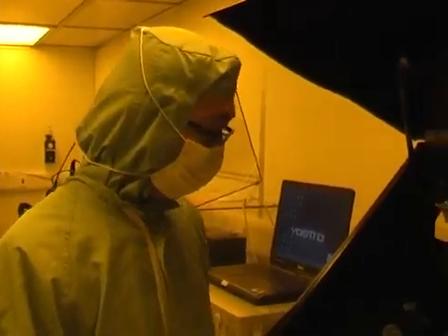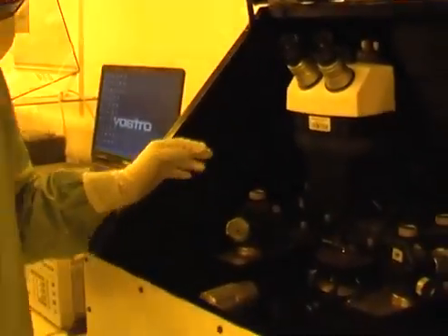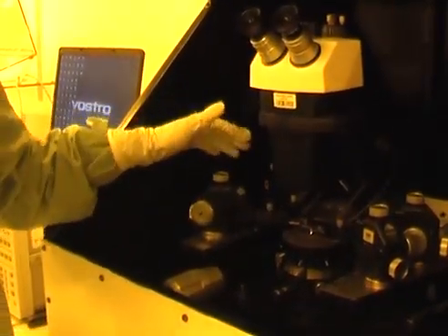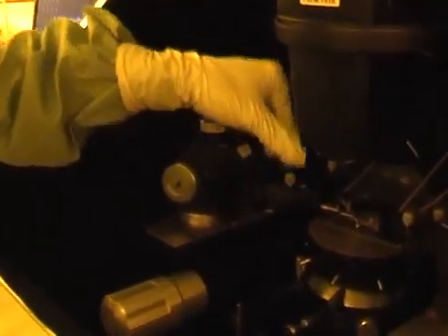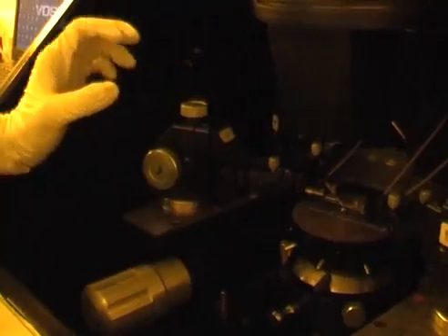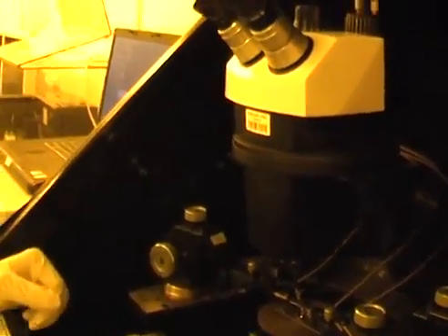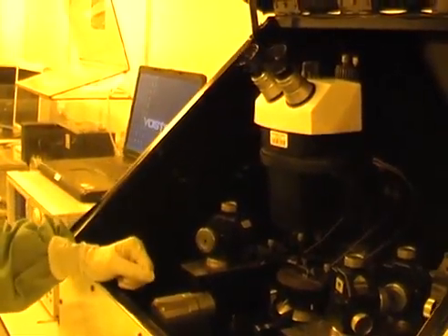And there's something you need to remember when using the ProbeStation: never over-tilt those movements for the probes, because those probes are very delicate and really fine. They can attack your sample, scratch your device, and you can even destroy the probe of the ProbeStation. So you need to remember, if you're not sure when using this equipment, it's better to ask staff around.